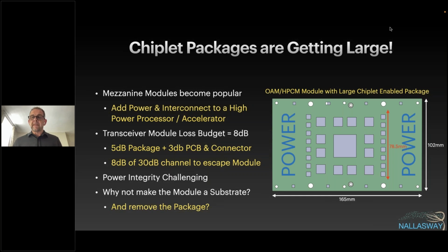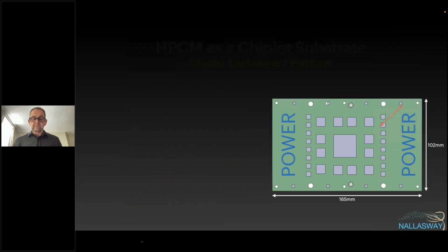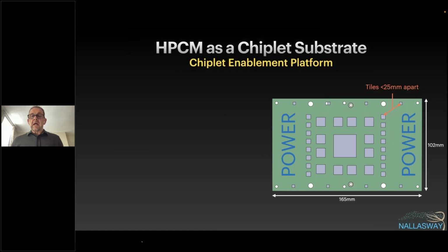So then you're basically saying that the new board would be the same complexity as the package itself, like a many-layer ABF type substrate, for example, just even bigger now. Right, you'd bring the HDI of a substrate, where you basically make the OAM PCB into a substrate material with the standard stack up there. Obviously, the boards are thicker, so there are challenges. But yes, effectively, you're giving all the substrate geometries. So this is organic, by the way. I'm not talking about advanced packaging. This is organic, so the 130 micron bump pitch or something like that is what we're assuming.